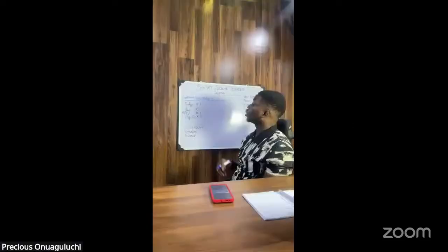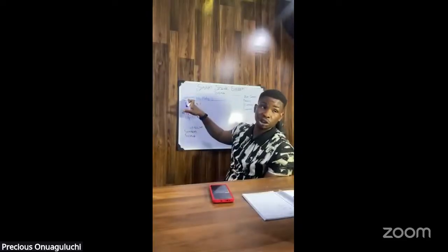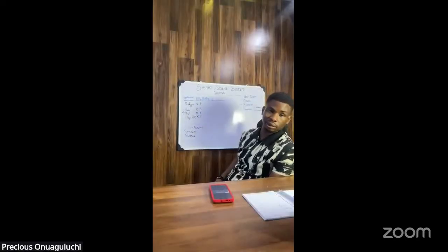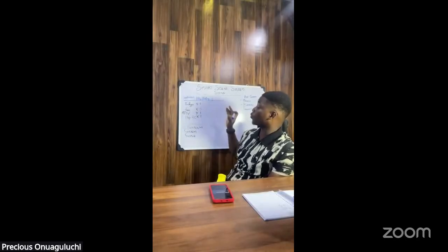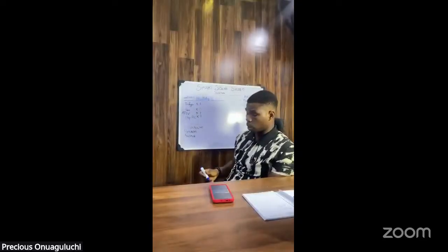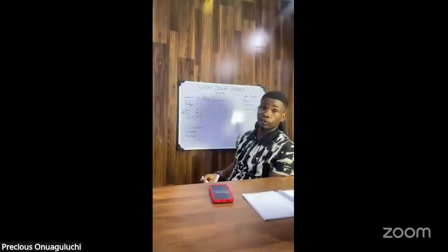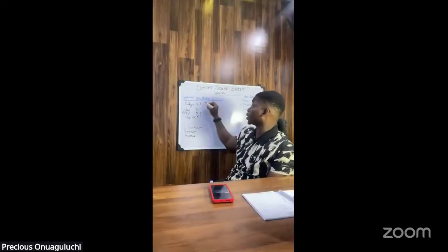Okay, so the first step I told you is write a list of all your appliances. Then the second step, write the quantity. How many appliances? I have one fridge, three fans, one TV, one AC. Then after that, you're going to go to the website I'm giving you, and you see a power rating for a lot of these appliances if you cannot find it on the devices.